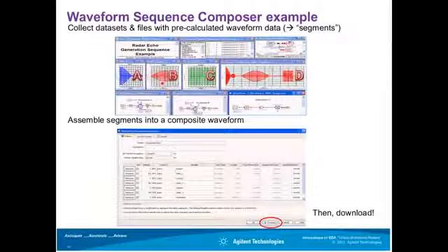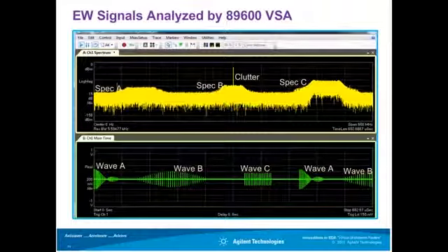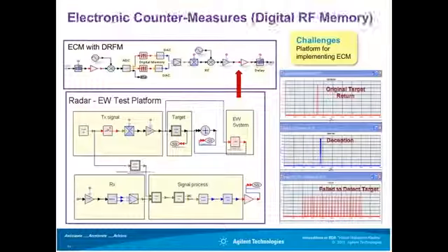At the beginning, you just need to generate simple waveforms, 1, 2, 3. Then use the waveform composer to define how long you want to use for A, for B, for C. And you insert zeros in between for the transmitter off time. Then use the UI and click on execution, and the signal will be generated. So it's very easy. This is complex waveform generation using the composer.